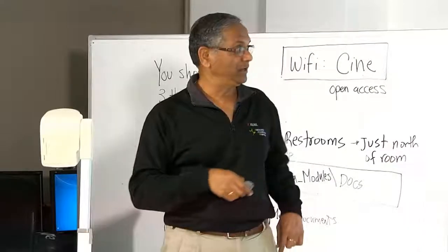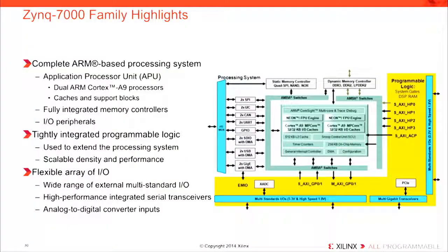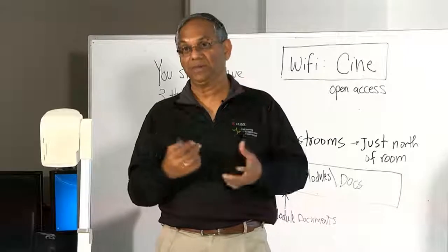Very important thing to keep in mind: Xilinx is processor first, programmable logic second, booting. Okay? So as you power it on, this block will be working, unlike the PowerPC based architecture where we had to configure the FPGA before we could use the PowerPC.